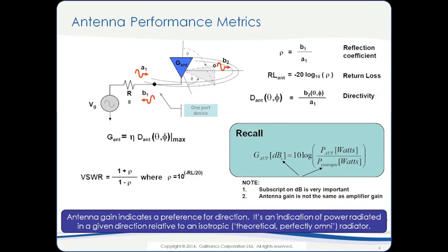And obviously the ratio of the radiated power to the accepted power is the antenna efficiency. That's a very important quantity. Unfortunately, we don't see that on data sheets for macro or even DAS and small cell antennas. But what it tells us is how lossy the antenna is. Typically in directive antennas, like the outdoor macro antennas, the loss in the system is not particularly critical, or it's not as critical as directivity is, or what is the beam width of the antenna in the elevation and the azimuth plane.